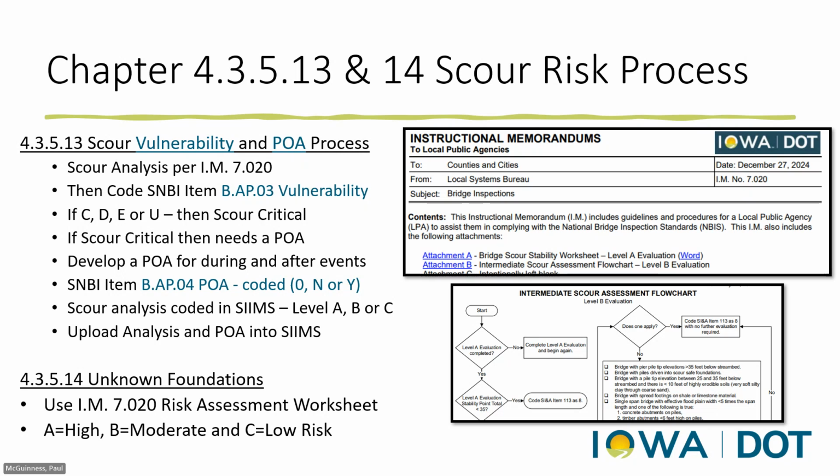One thing that has changed is the coding for the scour assessment. The SNBI has different coding than the old coding guide, so it's not a one-to-one comparison. You have to make sure you're using the right values there. And we will be updating the IM to reflect the SNBI coding in the future. Don't have a date for that yet, but that will be happening.